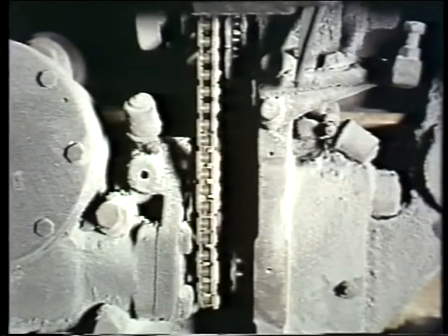Now, a long tube retractable soot blower is a bit different because its drive mechanism travels along with the element as it's extended and retracted. Rather than using a cam to actuate the valve, a triggering mechanism is tripped by the traveling drive as it goes out and returns. The limit switches that control the travel of the soot blower's drive and the element are external limit controls. And finally, the rotation may be driven by a chain and sprocket arrangement.